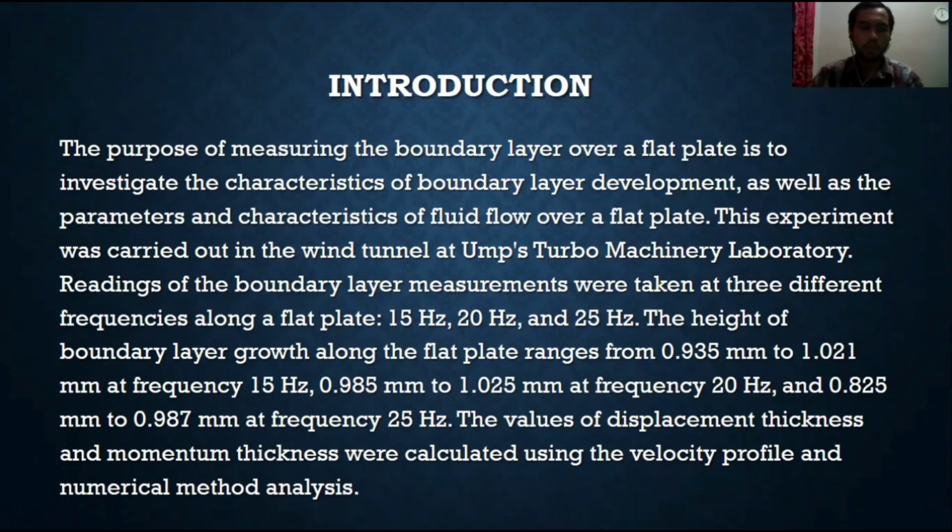For the introduction, the purpose of measuring the boundary layer of a flat plate is to investigate the characteristics of boundary layer development, as well as the parameters and characteristics of fluid flow over a flat plate. This experiment was carried out in the wind tunnel at the UMP Turbo Machinery Laboratory. Readings of the boundary layer measurement were taken at 3 different frequencies along a flat plate, which are 15 Hz, 20 Hz, and 35 Hz.